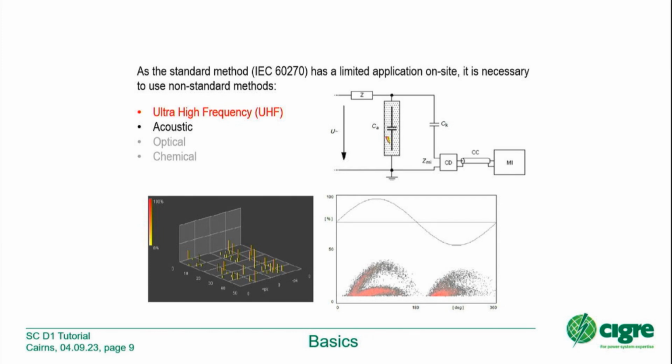Anyhow, people are working on that equipment. For 145 and 245 kV, and also some 420 kV GIS, they are delivered as a bay, assembled from smaller modules, if you think about 420 or 550 kV. This reduces workmanship on site, which will improve quality. So I think your way is a good way, your experience is good, and if you are looking for regular PD detection, that's also a good idea.